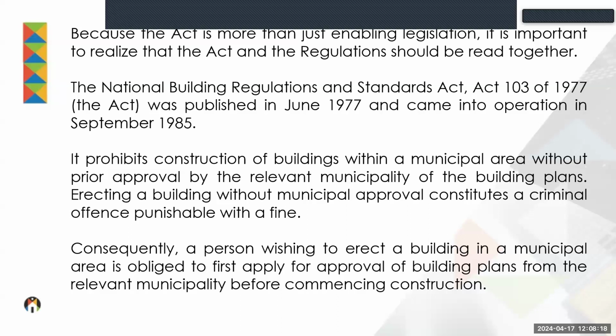So a person now wishing to erect a building in a municipal area is legally obliged to first apply for approval of building plans from the relevant municipality before they can commence with construction. And I want to highlight again what I've said earlier. If you go and read a few of the judgments made in the Constitutional Court, especially by Judge Jafta, it is said that non-compliance with the National Building Regulations constitutes a criminal offense. A lot of people have tried to water it down to say it's only an offense, so it only means that you maybe get a fine, etc.